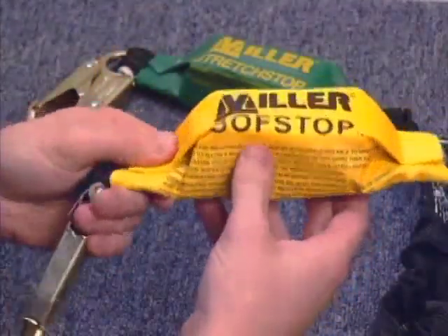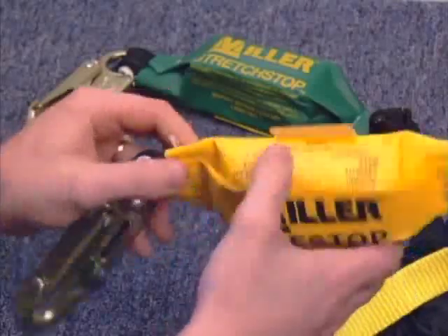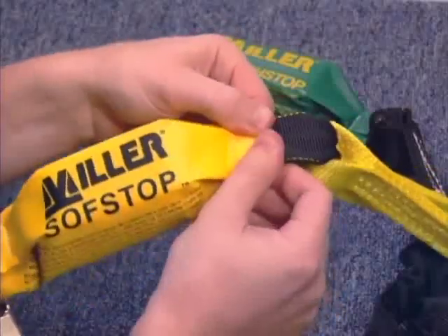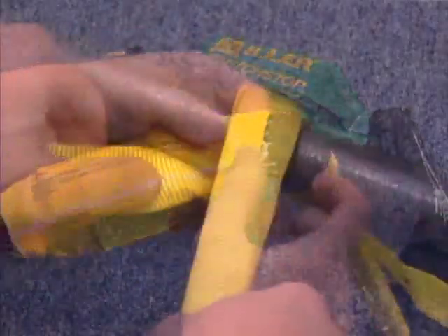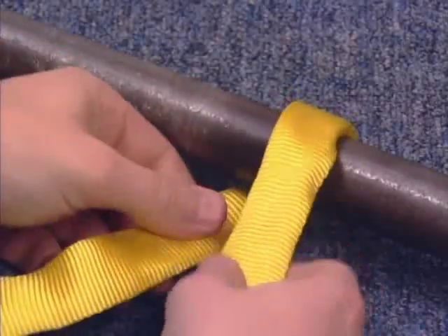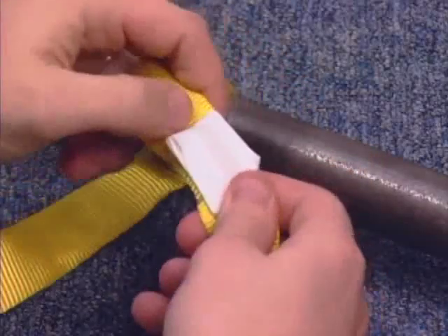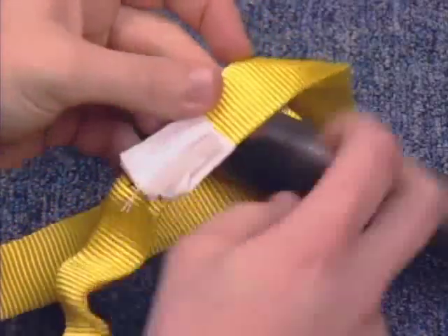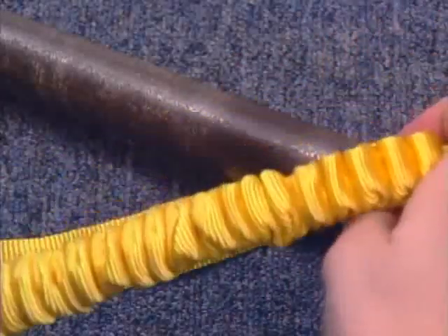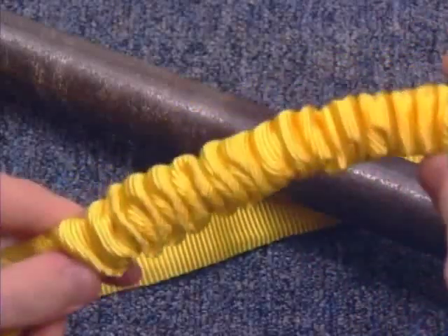The outer portion of a shock-absorbing pack should be inspected for tears or burn holes. Stitching at the points where the pack is attached to D-rings or lanyards should be inspected for damage. Lanyards with a shock-absorbing inner core should be examined similar to a web lanyard. However, also look for signs of deployment. This lanyard has a warning flag that indicates whether it has seen a fall. If the flag has been activated, is missing, or other signs of deployment are apparent, remove the lanyard from service.